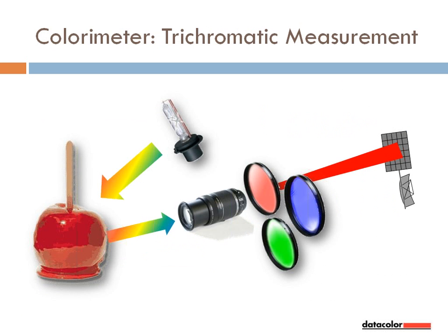Here's a simple schematic of a colorimeter. There is a lamp, a place to put the sample, a lens to capture and focus the light on a detector. In front of the detector are three filters, trichromatic, based on three primary colors, like human vision is. Classic colorimeters report color coordinates directly, specific to the light source and filters used in the instrument.